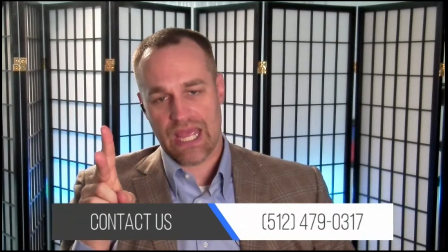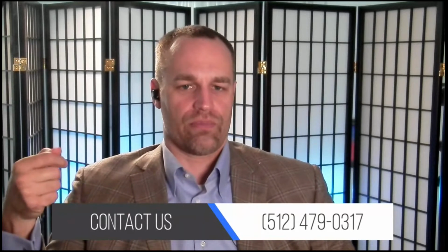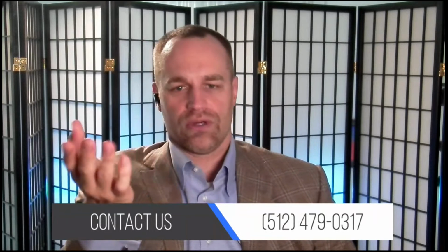Great question. As long as you're using a PoE device, there's two potential worst case scenarios that I'll talk about. If you just have a mode confusion where you've got a PoE switch that does mode B and your PoE device only does mode A, the worst situation is it's just not going to power on. And 24-volt passive is designed so that you can't accidentally damage a normal PoE device by plugging. If I plugged a 24-volt passive injector into a traditional PoE camera or phone, it just won't power on. It's not going to cause any damage.